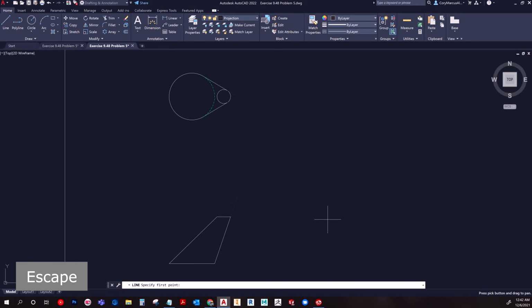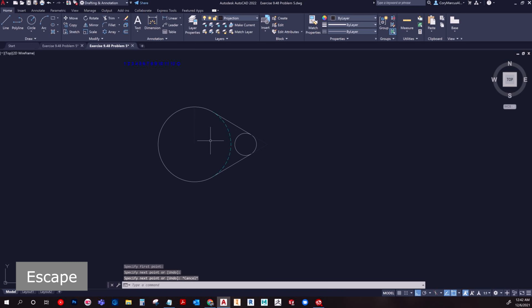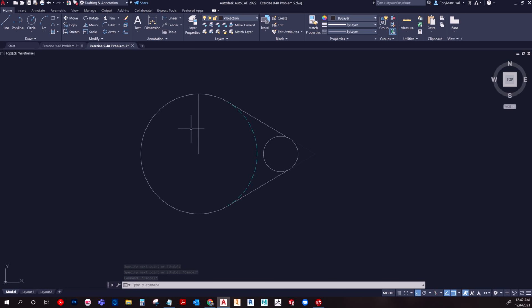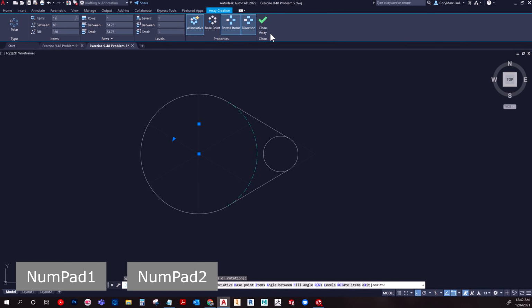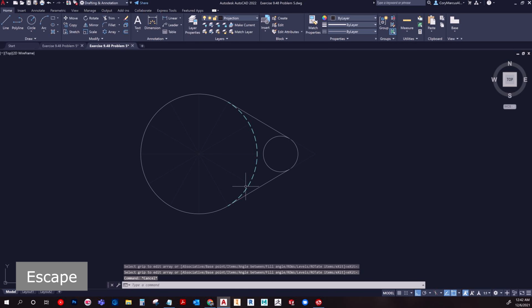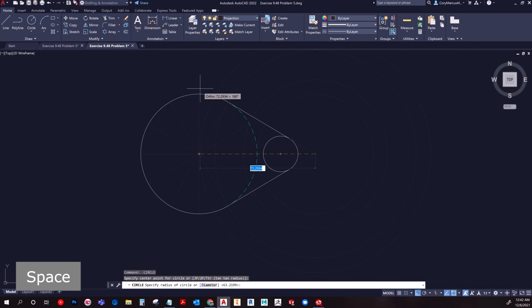So the first thing we need to do is to go ahead and subdivide this bottom face. And then we'll go ahead and do the top part here a little different. So for now, the easiest way to go about this is to draw a vertical line, and then select the line, select array, and we'll choose the center and give it a value of 12 because we're going to do the same as what it shows. So from here, we just need to go through and snap from each origin point to each ending of each face, figurative face anyways.